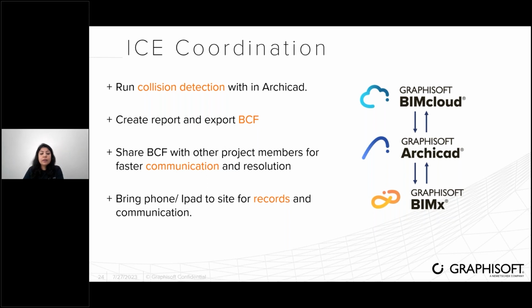So within Archicad, you can run collision detection, export the report as BCF to BIMcloud, and it can be shared with other users who can actually bring that BCF inside their model as well, and review what the issues are. That way, your communication is faster, resolution is on time.